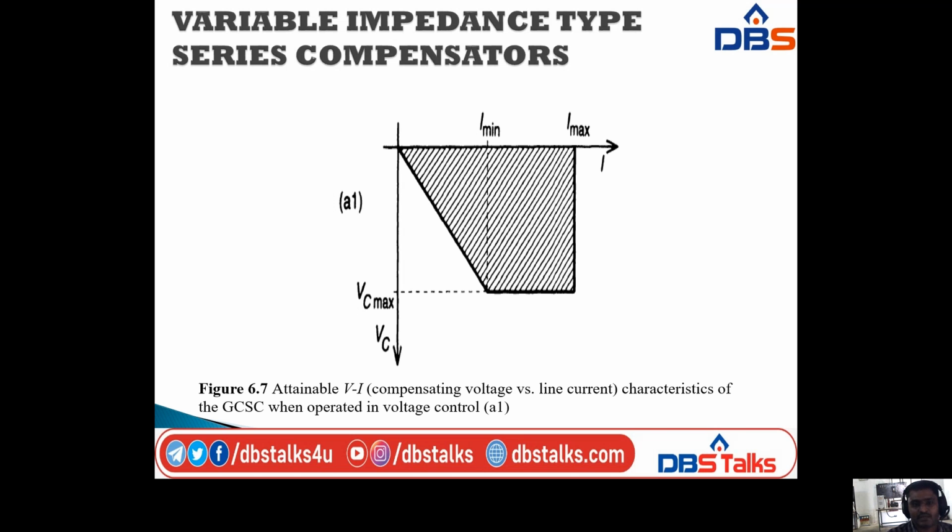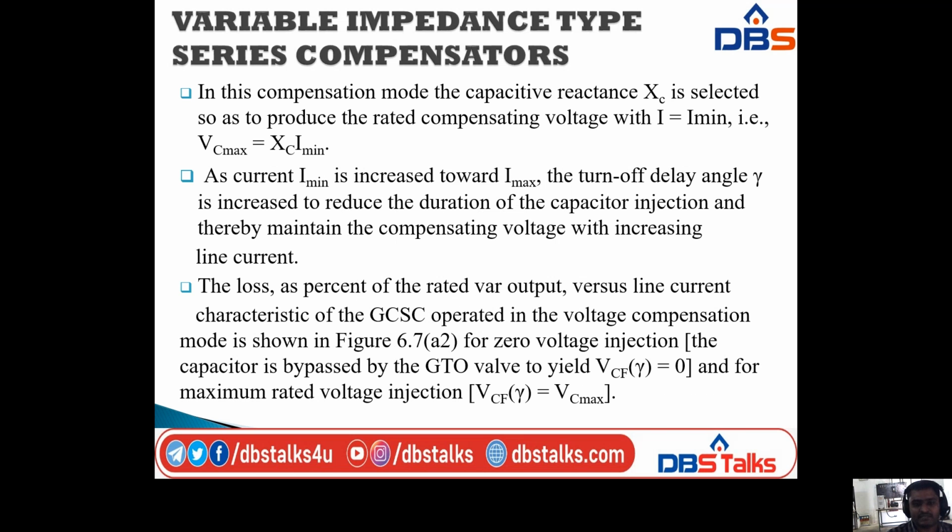In this compensation mode, that is in the a1 diagram mode, the capacitive reactance Xc is selected so as to produce the rated compensating voltage with I equal to I minimum, that is VC maximum is equal to Xc times I minimum. As current is increased from I minimum towards I maximum, the turn-off delay angle gamma is increased to reduce the duration of the capacitor injection and thereby maintain the compensating voltage with increasing line current.